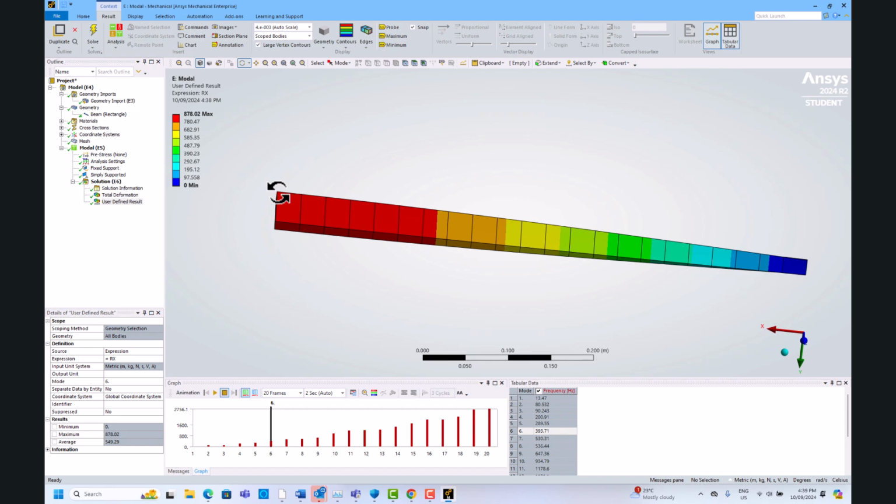But if you learn about mode shapes, the amplitude of the mode shape doesn't have physical meaning, so you just look at the shape. It might be exaggerated, but it should be in radians. Well, it's not in radians, but it's proportional to radians.